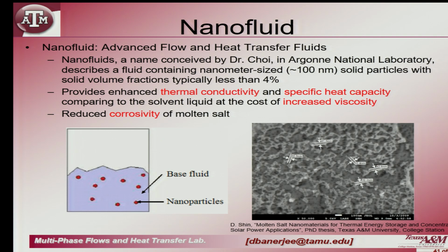So, for your nanofluid experiment to be valid, the first thing you have to prove is that the nanofluid sample you are working with is a stable colloidal solution. If it is not, then you will get all sorts of weird answers and unrepeatable experiments. So, repeatability is the first key parameter to make sure that your experiment has been done in a valid way. A nanofluid should be composed of nanoparticles that form a stable colloidal solution. Unless it forms a stable colloidal solution, you cannot call it a nanofluid. Just putting nanoparticles in a solution does not mean it is a nanofluid.